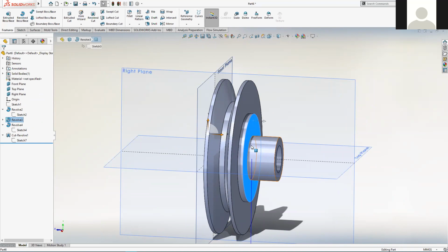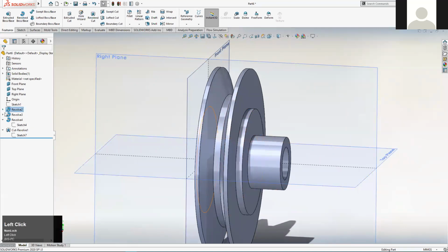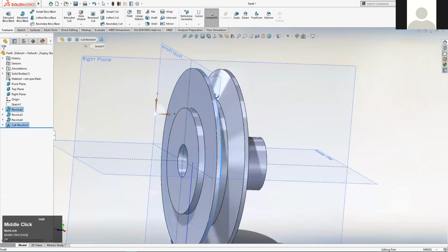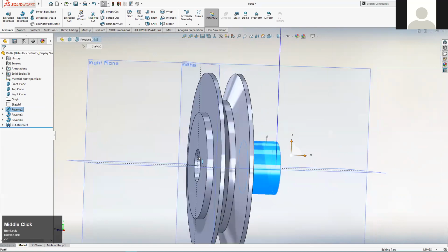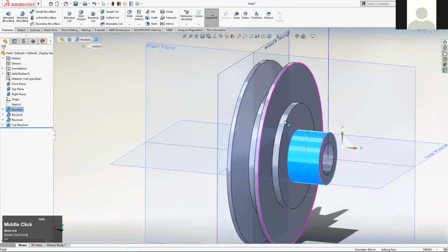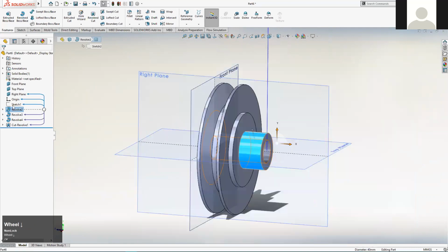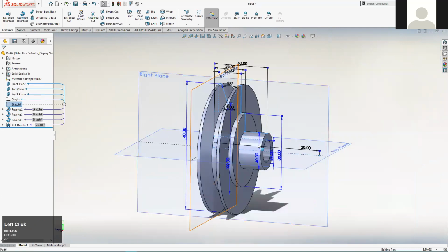But at this level that you're learning SolidWorks at, I would not mark either method down. It's just so that you're aware there are multiple paths to get to the same geometry. So you can set things up as multiple features and try and put some logic in terms of, I class that V shape as a feature. I also class this major shaft down here as a feature. And try and break things up logically. Or, if you feel confident enough, you can go for it and enclose them all in a single feature.